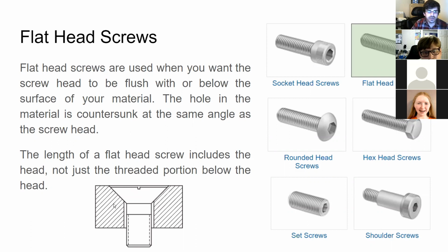Also, since the angles are self-aligning, if you have a hole pattern with 2 or 4 or 6 countersunk screws, they're all going to be trying to self-align and fighting against each other. So if your tolerances aren't good enough, you might not be able to even get it to go together properly, which is a disadvantage.